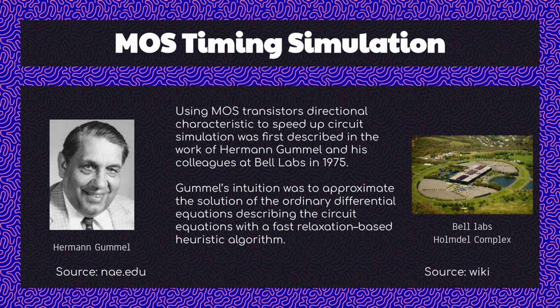In MOS timing simulation, the insight was to recognize that when analyzing the timing of a digital circuit, it is not important to have accurate waveforms as long as the switching events can be placed in time correctly. Fast circuit simulation is still based on this idea today. Hermann Gummel and his colleagues described work on this idea at Bell Labs and published it in 1975.